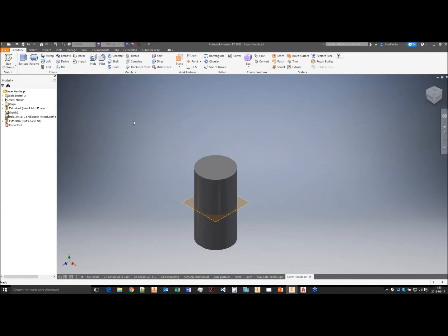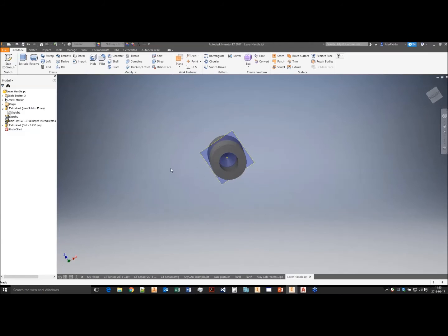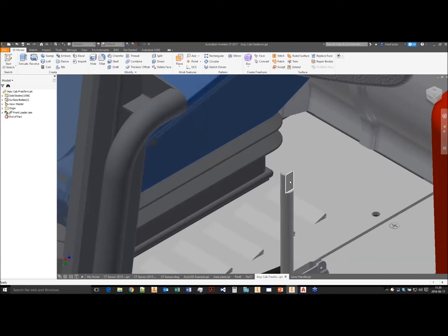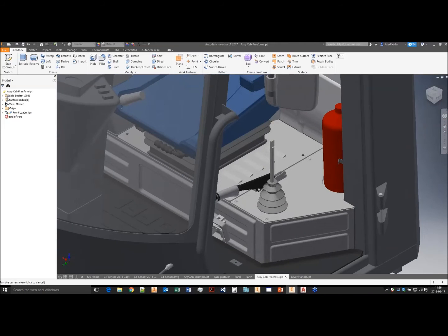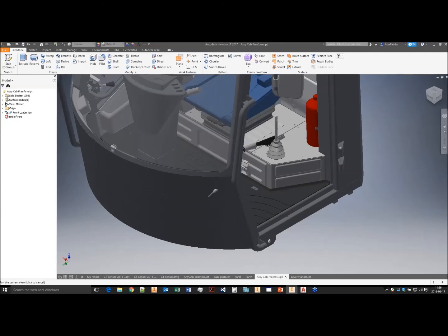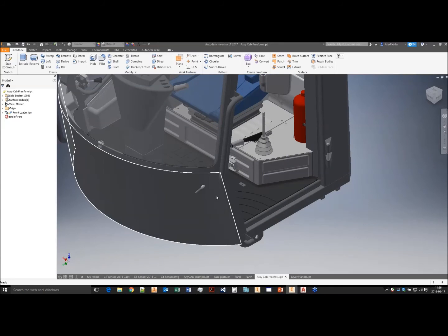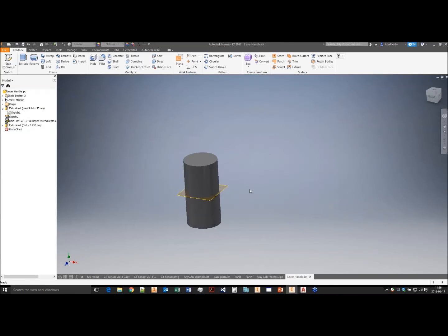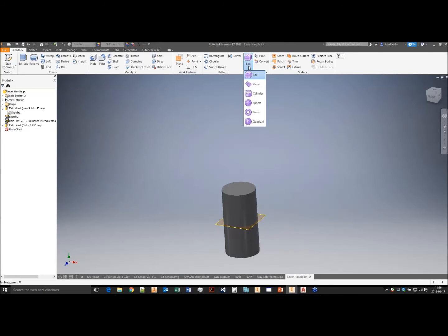Right, once that's loaded, this is just a basic Inventor part that has a threaded hole in the bottom. So this would effectively screw onto here. I can't put that into that part in Inventor LT because, as I say before, it can't work with assemblies. But what I can do in here is I can create a freeform.